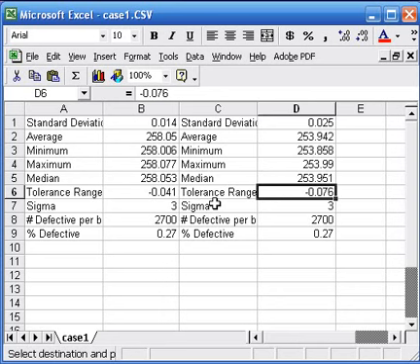the whole range. And because you're doing the tolerance analysis in the conceptual stage of the design, it can have a tremendous effect on the overall cost and performance of the product, because you can order your tooling first. You can also check your manufacturing capabilities up front, and this becomes especially useful if you're going to outsource the manufacturing, so you can validate a vendor.